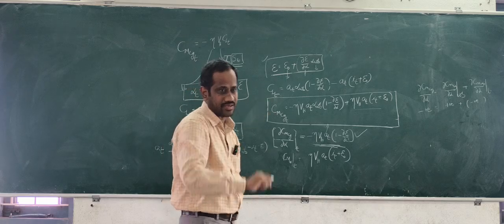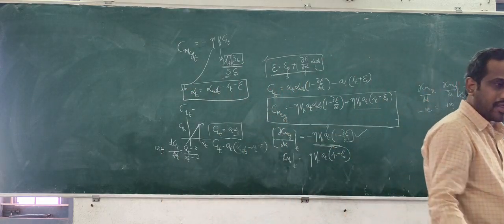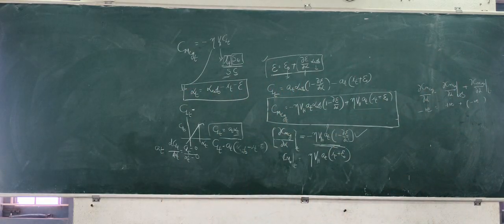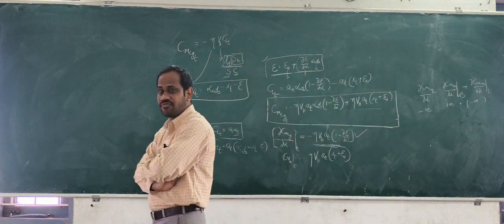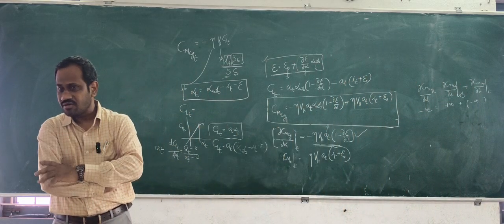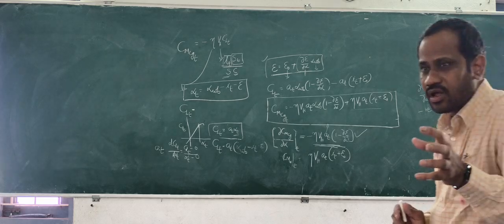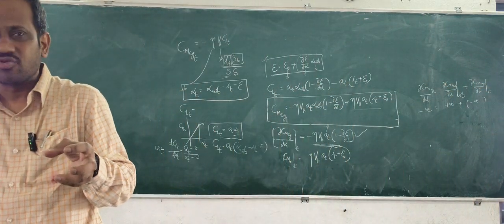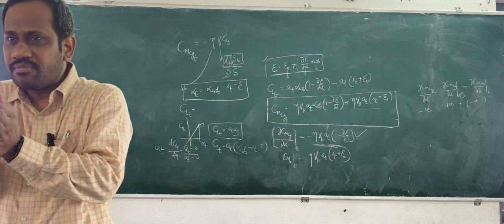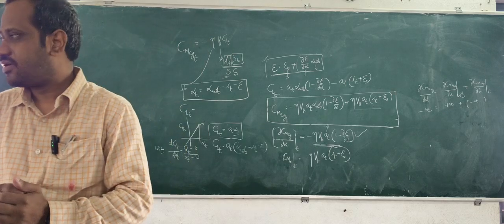Don't write suffix t. For the whole aeroplane, Cm naught can be positive and the whole aeroplane's dou CMCG by dou alpha negative by keeping a tail surface aft of the wing. Is it understood now? Design essence: if one component is contributing negatively, adding another component suitably, the summation should become the required sign.